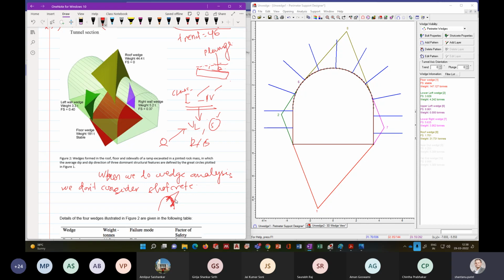But it's very difficult, in a big cavern or a tunnel, to know whether the shotcrete thickness is uniform in that location or not. So it's better not to rely on the shotcrete thickness and just rely on your rock bolt. So when we design the tunnel, we don't consider the shotcrete, only whether it is stable with the rock bolt or not. But if you are sure for your case that your shotcrete thickness is uniform everywhere, then you can consider shotcrete. Is this clear?